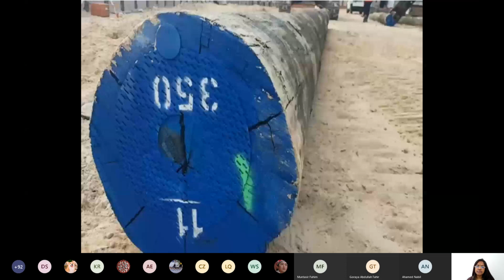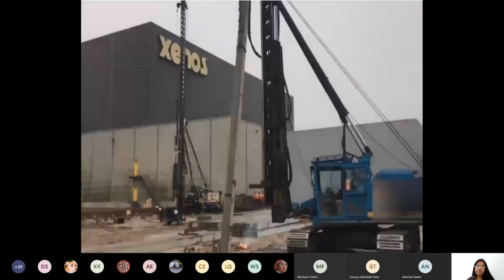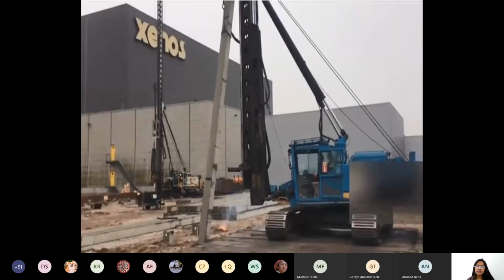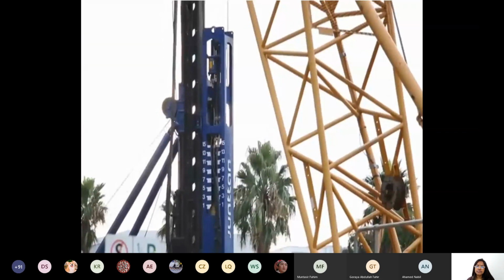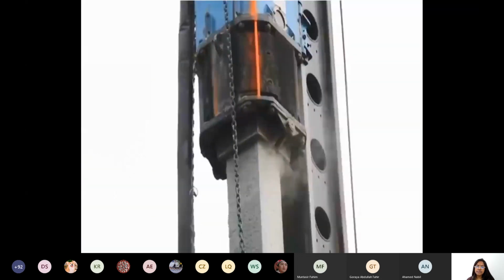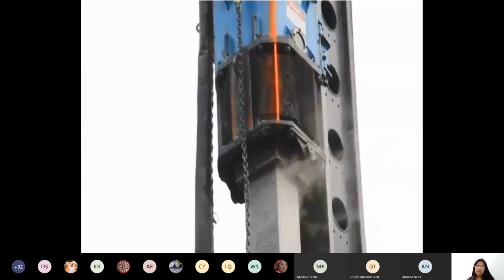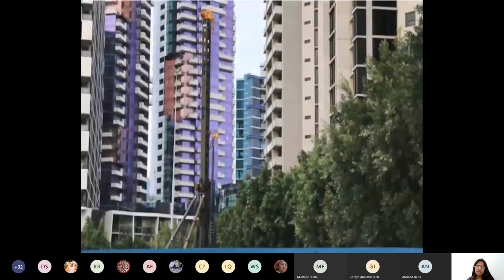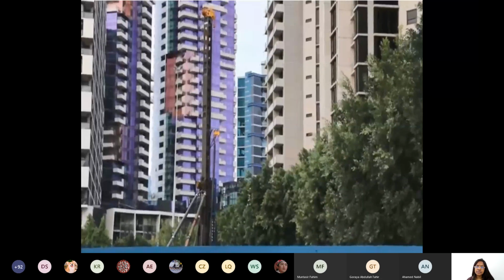For example, a Yuntan PM25 pile driving rig with a Yuntan HHK5 7S impact hammer has the ability to drive 30-meter piles of approximately 850 millimeter diameter in the ground, thanks to its 103 kNm energy from a maximum drop height of 1.5 meters with anywhere between 30 and 100 blows per minute.